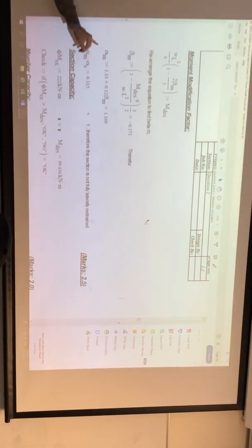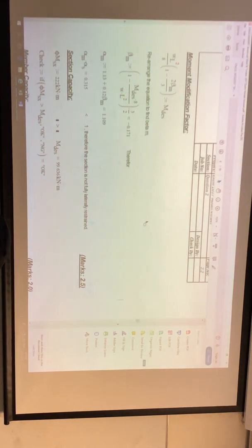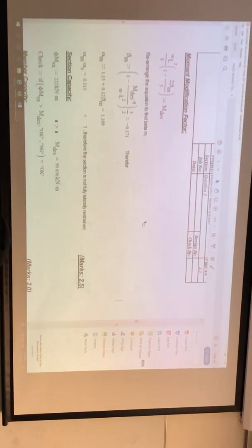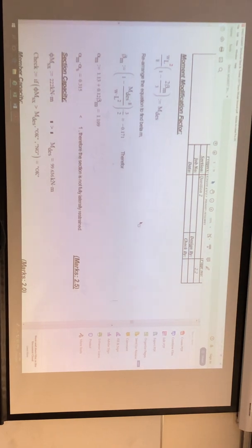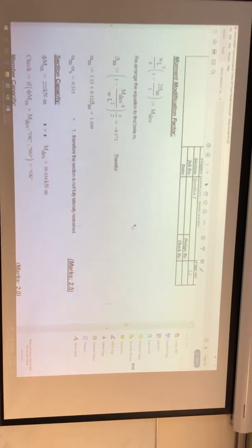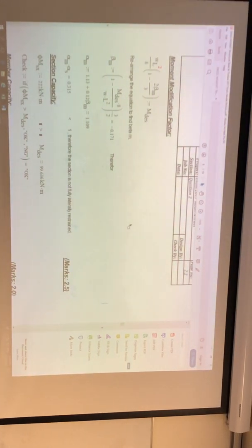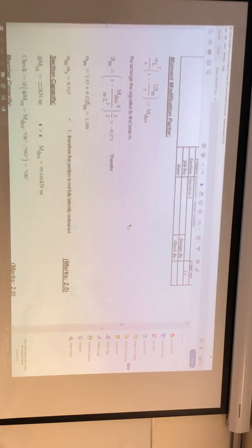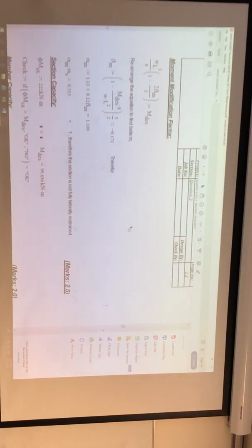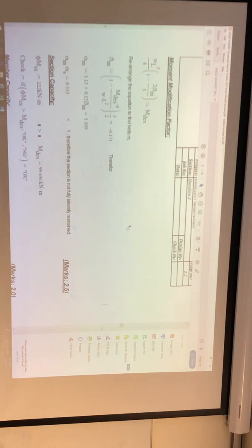Most of you got it right. And the assignment, we get around 1.13. When it's a simply supported beam, straight away it's 1.13. When it's a simply supported beam with a point load and a triangular moment, straight away it's 1.36. It's that simple, but in any exam, you have to use the proper way.